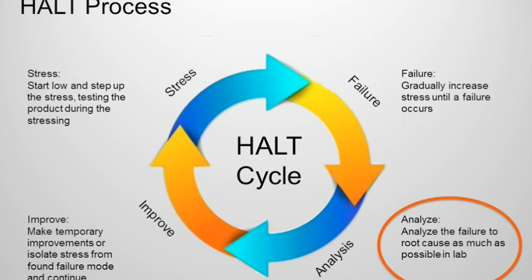And this is one of the reasons whenever you develop a HALT test, I push very hard to have the design engineers attend the test, because with some other tests, the engineers might feel like being present isn't important. And that is because they set up specific conditions and they're interested in if the unit has passed or failed it. But that's not the value of HALT. The value of HALT is causing the failure and getting a chance to observe it.